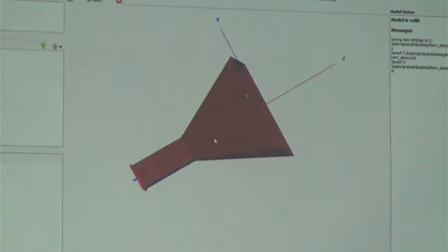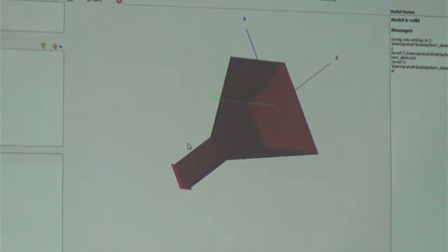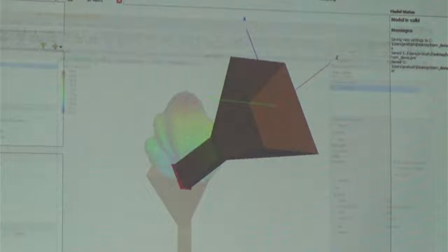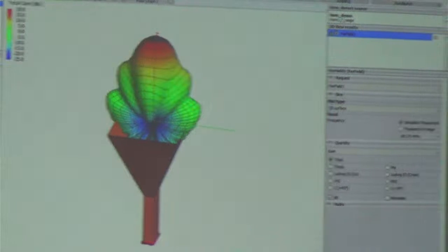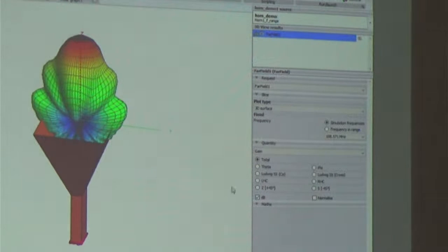So what are the quantities of interest here? Once you have a design, you run a simulation. That simulation gives you electric field patterns, and there are things that you can physically translate to what you will measure. Let me show you those. The very first thing you would want to see is the beam pattern. For this, we ran this simulation. This antenna was designed at lambda equals 3 meters, 100 megahertz. And right now, I don't know which frequency this is, 108 megahertz.